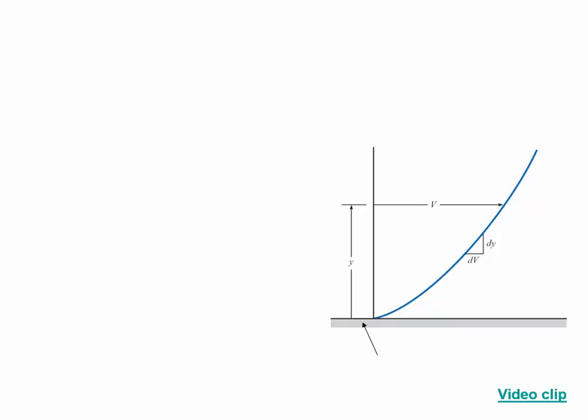And then dy is how far vertically we're getting from the bottom of the stream. You can see that the velocity is increasing fast at first, but then it begins to taper off a little bit. It's a non-linear velocity profile. That's because, as you get further away from that solid surface, it speeds up quickly, but then it's like diminishing returns. Getting a little bit further away from this surface that's so far down, it's exerting less of an influence the further we get from the bottom of the stream.